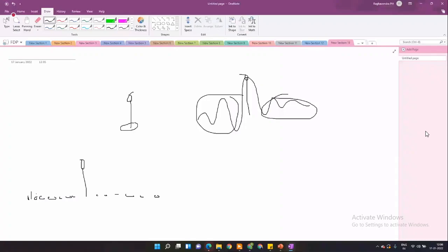Once I pass it through the root raised cosine function, it will look like this. Now, although this is discrete, you can say that this somewhat looks like a root raised cosine pulse. You trace this, it will look like a root raised cosine pulse. Which is why we add some zeros before and after our samples.